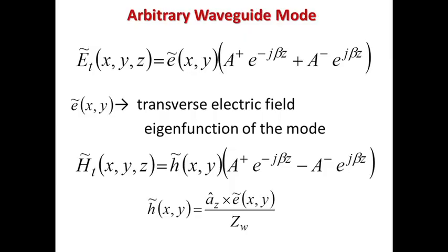So, you can make that impedance so defined from voltage by current either as wave impedance, or you can normalize that. These 2 choices are existing. So, if this is done, then at a terminal plane we can uniquely define voltage and current. Obviously, voltage and current will propagate in the z direction in the form of a wave, but the terminal voltage and current, they will be unique.